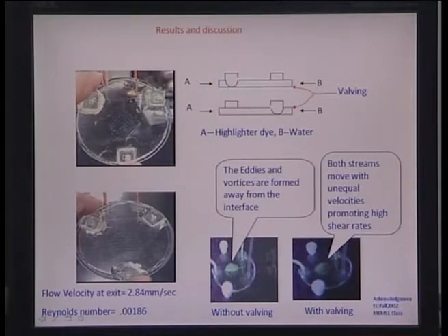So, when you actually use these structures, whether it is the tube bank kind of structure or the triangular type, you have really, as you see here, the fluorescence dye and the water flowing parallelly. What is interesting to observe here is that although there are a lot of these small PDMS pillars around which the fluid should rotate and it should create local vortices or eddies, they are too small to cause any mass transport, particularly across the interfacial layer.